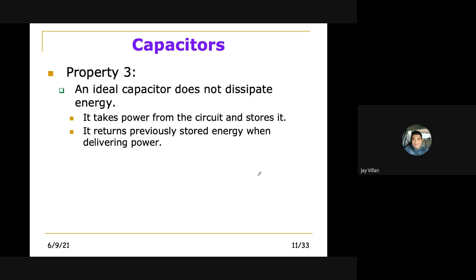In your electronics one, in the design of a power supply using a bridge rectifier, what you will get after rectification is still not a straight line. So in order to filter this line, you need to have a capacitor.